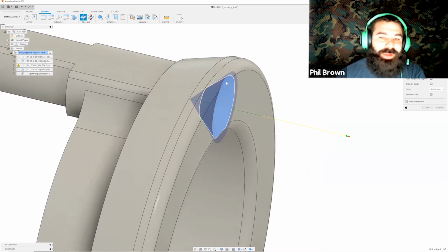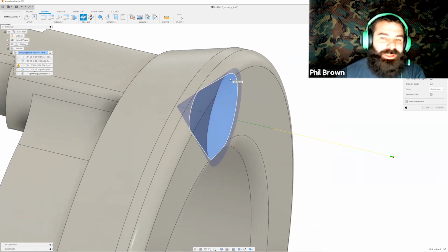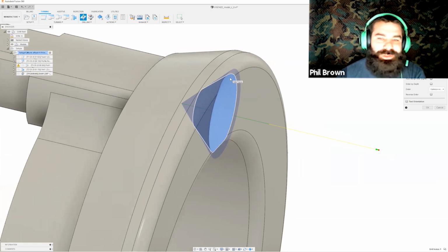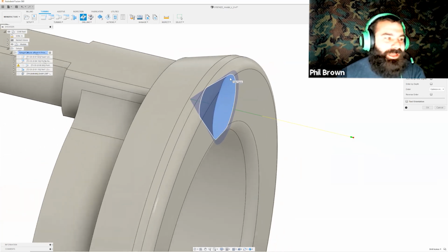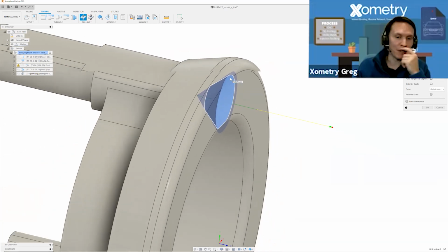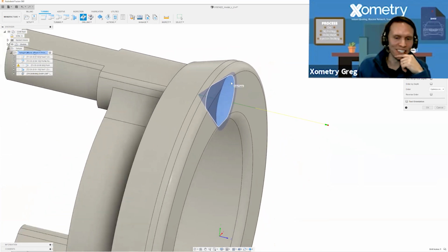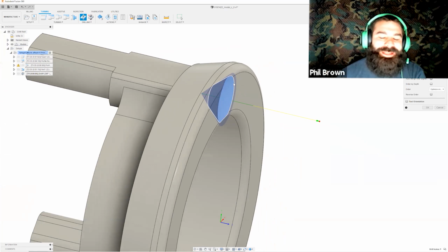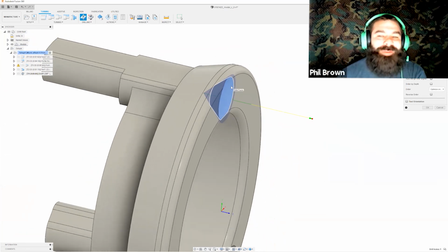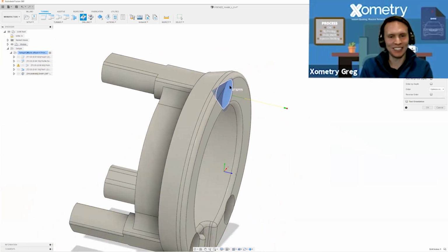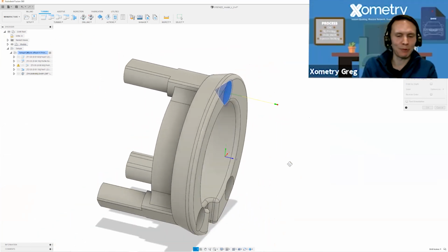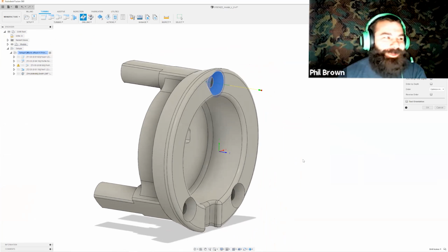One thing I also am recognizing here, Greg, is it looks like those angles on those holes are not a 90-degree countersink, correct? I need to measure that, but yeah, it looks a little narrow. It looks a little off. The good news is the customer okayed us to use this in the event that I did change my tooltip angle. So Phil reached out to Casey, who confirmed with the customer that this is an acceptable change. Correct. So that's the nice thing about giving feedback on a part before you take it.